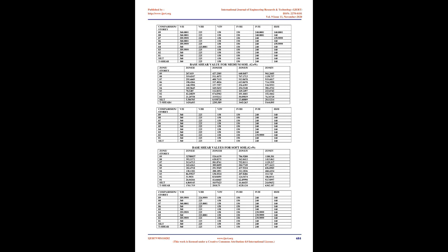3.7 Vertical layout. The earthquake forces developed at different floor levels in a building need to be brought along the height to the ground by the shortest path. Any deviation or discontinuity in the load transfer path results in poor performance. Buildings with vertical setbacks cause a sudden jump in earthquake forces at the level of discontinuity.